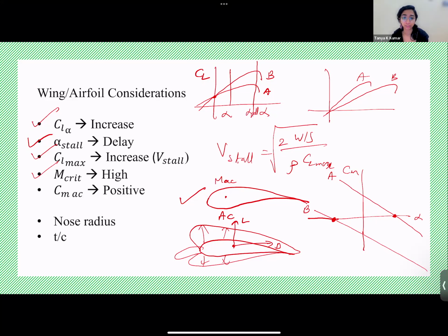So because of this pressure difference, you have this lift and drag. Why is there a moment? So this is your aerodynamic center. What is the point where lift and drag, the aerodynamic forces, are acting? CG. I didn't hear you. Can you repeat? CG. Okay, it's not CG. It will be center of pressure.